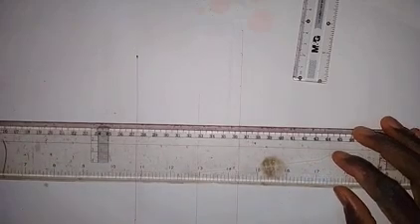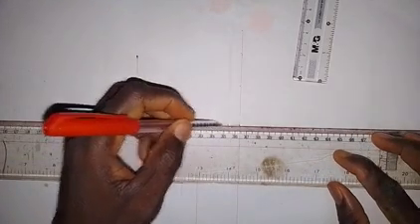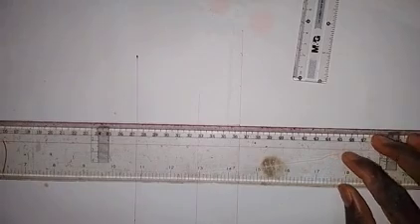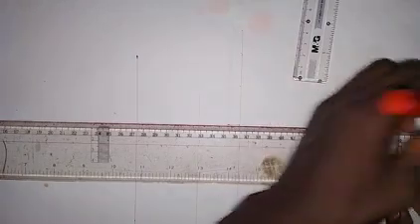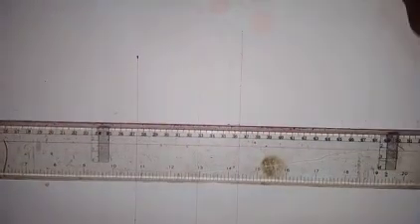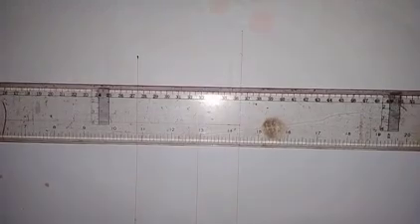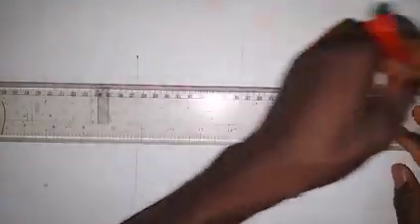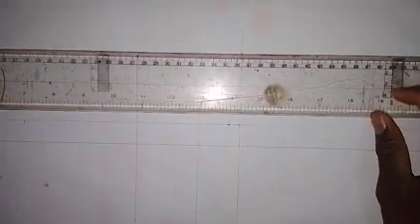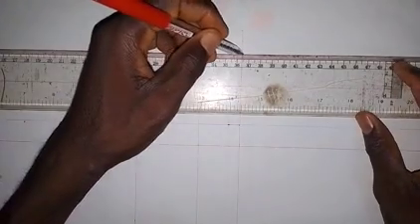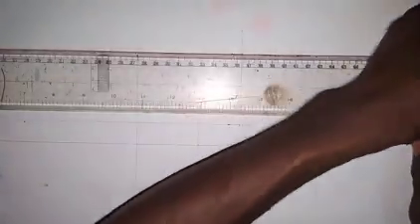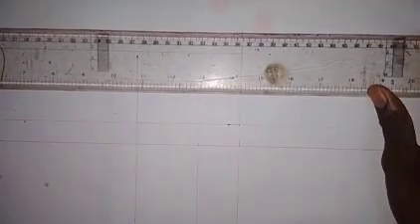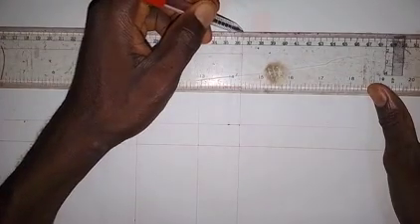So I believe. Okay, so what I need to do now is draw a horizontal line through each of these points, and these horizontal lines must go to both the left and right because of the end elevations that we are going to produce. Okay, so I will also draw this. And here also I will draw a horizontal line to both sides, and then here I will draw a horizontal line to both sides.